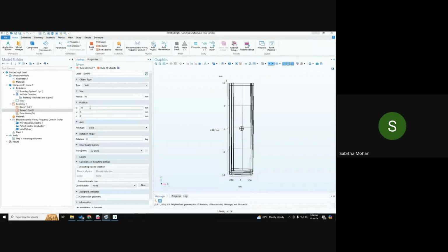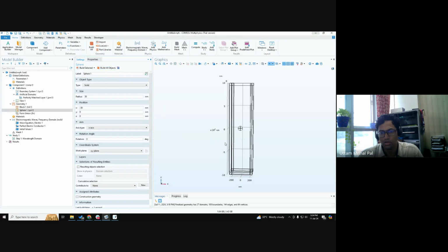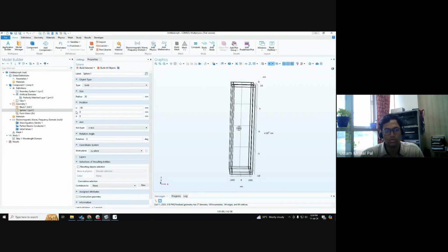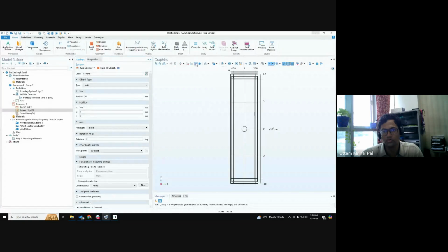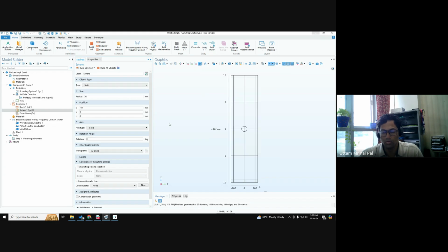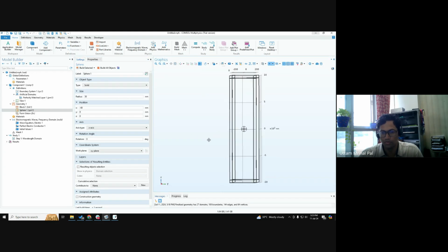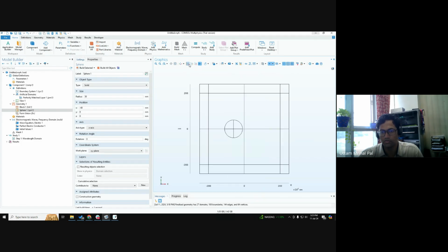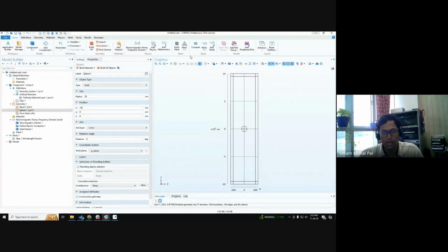So it looks good, the position is now 30 nanometers. Maybe a bit more, 60 nanometers. There is also the XY view, so you can change the different views and make it an orthographic projection, so that there are no multiple boundaries and it's a perfect XY plane or YZ plane.